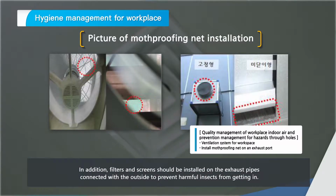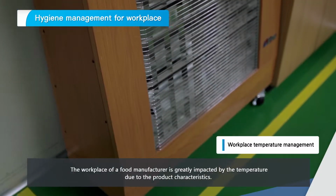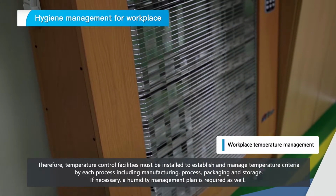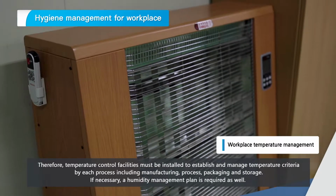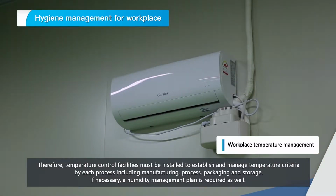In addition, filters and screens should be installed on the exhaust pipes connected with the outside to prevent harmful insects from getting in. The workplace of a food manufacturer is greatly impacted by the temperature due to the product characteristics. Therefore, temperature control facilities must be installed to establish and manage temperature criteria by each process, including manufacturing, process, packaging, and storage. If necessary, a humidity management plan is required as well.